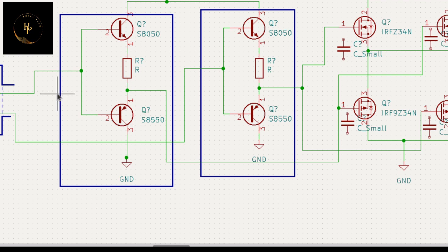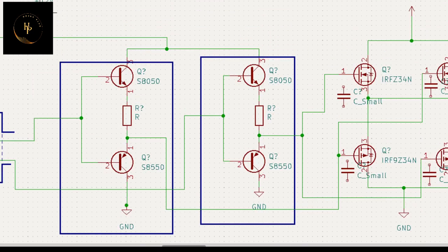Why? I tell you. After some time, when this pulse is going high and this transistor is on, then the power, that is your power line, that is 12 volt power, comes through this transistor and gets here. But in that moment, your transistor base is high and the emitter is also high, but both are the same because there is a resistance, so this voltage is lower than the base, that means that transistor is off.